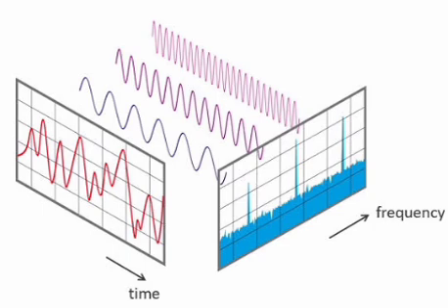Characterization of LTI systems using Laplace transform: causality. The ROC associated with the system function for a causal system is a right half plane. For a system with a rational transfer function, causality of the system is equivalent to the ROC being the right half plane to the right of the rightmost pole. The system is anti-causal if its impulse response h of t is not equal to 0 for t less than 0. An LTI system is stable if and only if the ROC of its system function H of s includes the j omega axis. A causal system with rational system function H of s is stable if and only if all the poles of H of s lie in the left half of the s plane, that is, all of the poles have negative real parts.